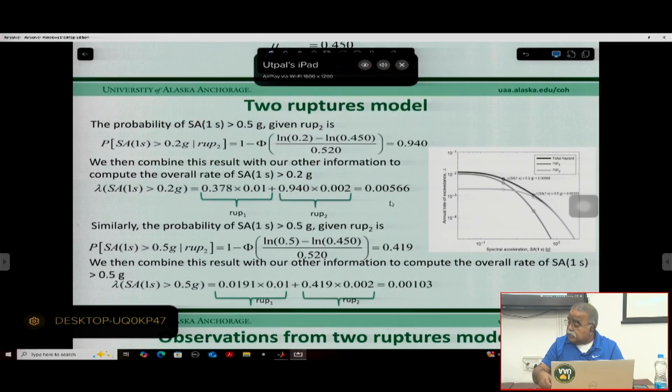Say suppose these are the two ruptures. That means two places, right? Two different faults have two different ruptures, so these are the two different fault things. But if I wish to have a uniform level, they are following different hazard curves. Whenever I am trying to do it, I will always take the 0.0046 and draw this line, because that's a 2500 years probability of exceedance, or 2% probability of exceedance in 50 years.